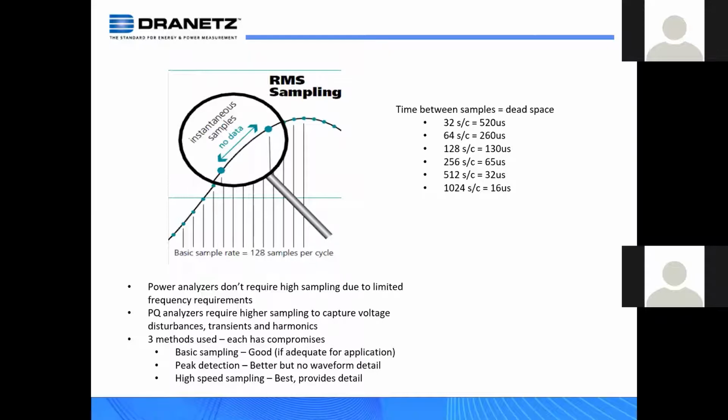Other instrumentation may say, like as an example, it digitizes at 1,024 samples per cycle. However, that may be for 1 channel. So if you have 2 channels, that's 512 samples per cycle. 8 channels, that's 128 samples per cycle, okay, on 4 voltage and 4 current. So just pay attention, just buyer beware, just pay attention to those sorts of specifications, because there's some gotchas there.